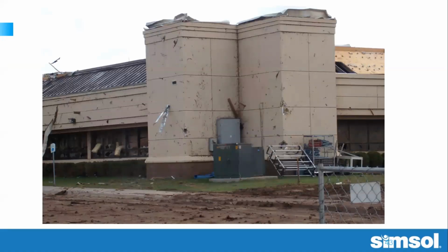Again, take a look at this. We've got pretty much damage up and down. Notice the metal roof is intact on the left side of the photograph, but it's mostly missing on the right side, including some of the decking. Take a good look there in the middle of the photograph, that nice piece of metal flashing that used to be up on top, jammed into the building like a spear. There's another piece of flashing toward the left of the photograph jammed into the building like a spear. This again is all wind related damage. Notice there's no damage down low, and you've got a lot of high damage.